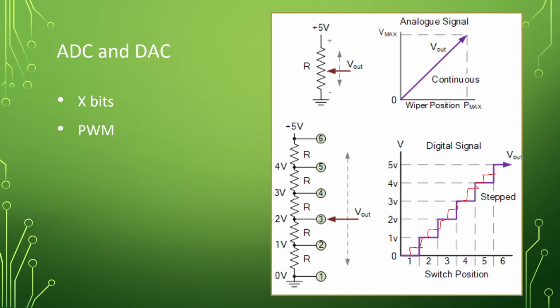Option two is you could find a temperature sensor with just a smaller range. If you're trying to keep a room at 50 degrees, do you really need between 0 and 256? No. You need between probably 40 and 80 or something like that. So you could find a temperature sensor where the range is smaller, so you would have fewer degrees over that entire range, which would increase your resolution. So with analog, there's so many little funky games that you have to play.